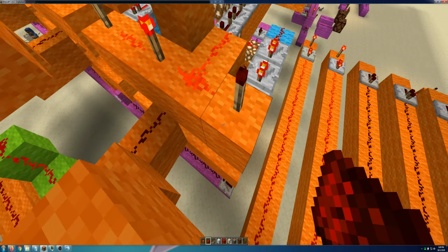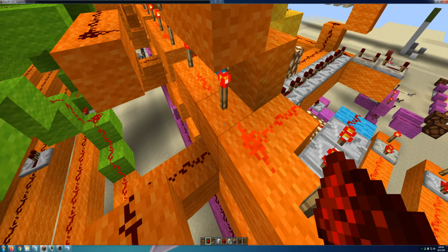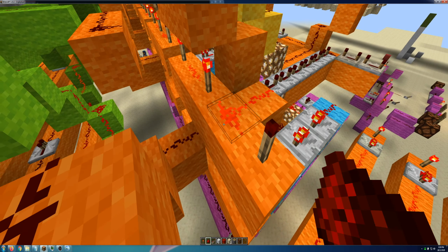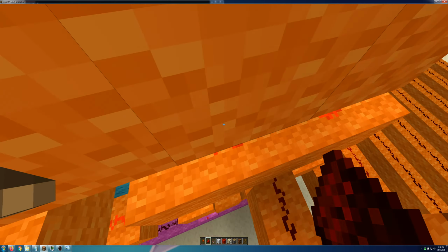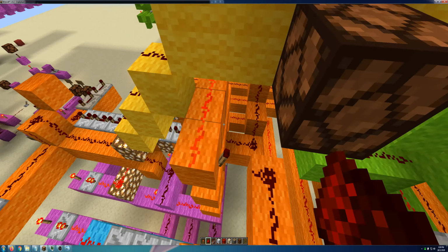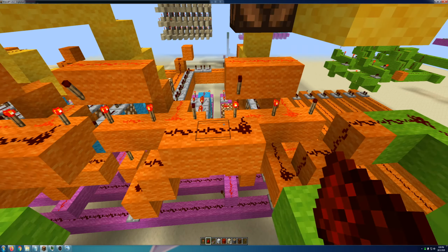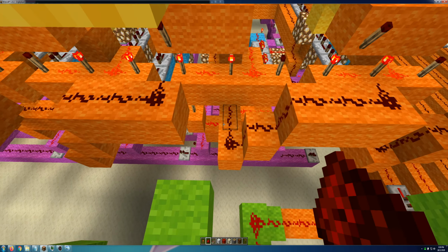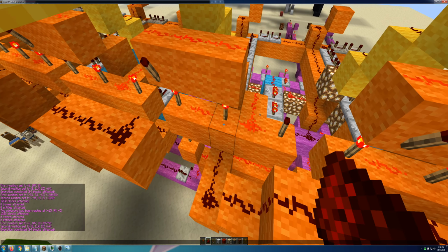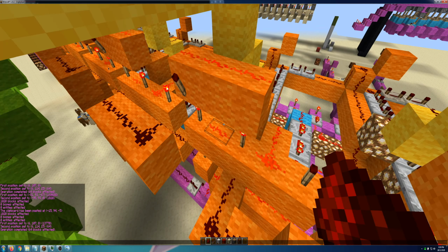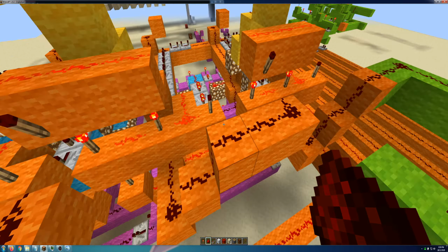And so here we have the first AND gate, and here we have the input for okay, it's time to turn on. If this is off, then that will determine that the other area should be inverted. And if that should be inverted, then the output, which is determined up here because there's not enough space, will just simply say, hey, move on to the next one. And that will go into the same place that that pulse goes into. And if again, this row is not selected because there's no torches down there, it will then go on to the next one. And it will keep doing that, and it will keep skipping pixels and rows until it encounters one that's on. And only then will it actually output a signal.